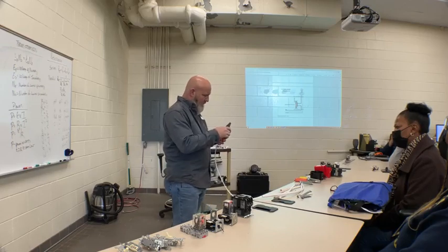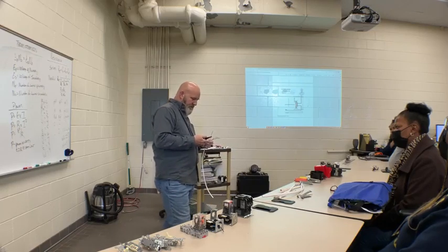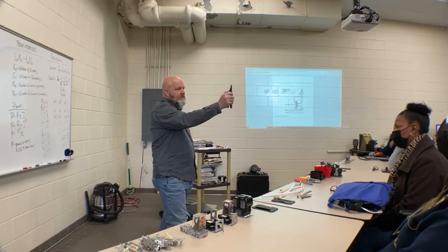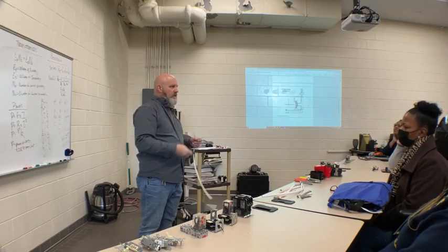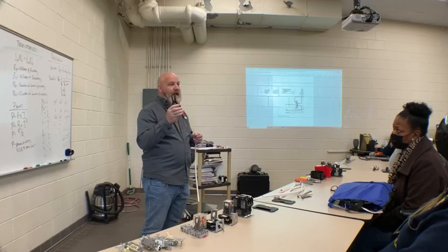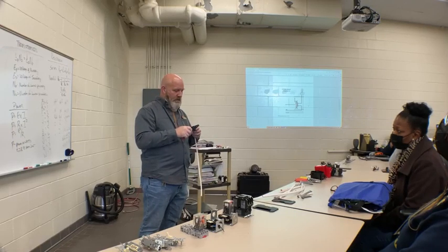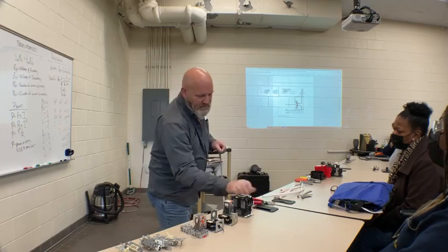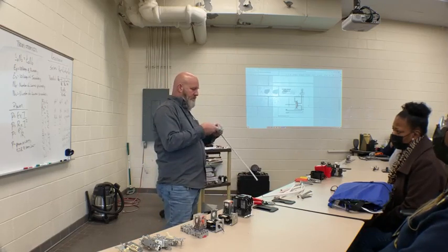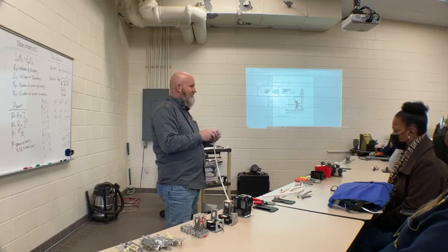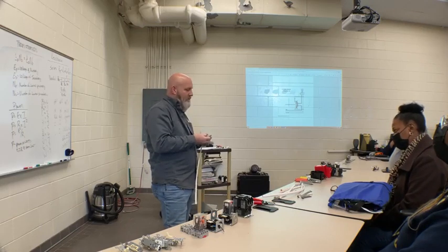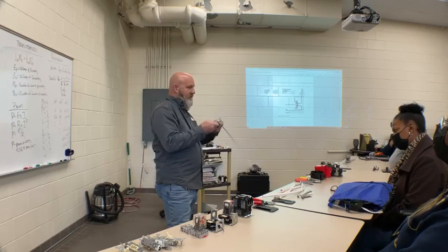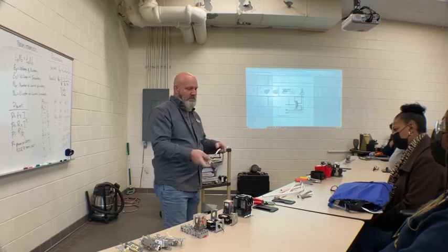Now, here's where everybody gets lost. They don't know this exists. There's a hole on each side of these wire strippers. And I have to teach students this. That is so you can bend your wire to fit nicely around the screw. Everybody gets needle nose pliers and tries to do it, but this fits very nicely around the screw.